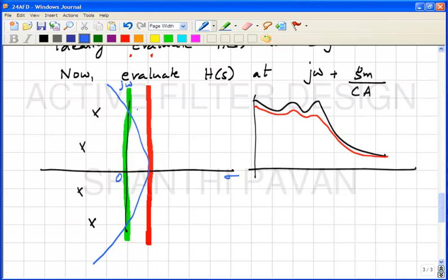Depending on the parasitic pole and the finite gain, it seems like there is one point here where the response of the non-ideal filter is the same as the response of the ideal filter. This is correct? Okay. And therefore, what must be happening at that particular frequency? The non-ideality due to finite gain is compensated by parasitic pole.